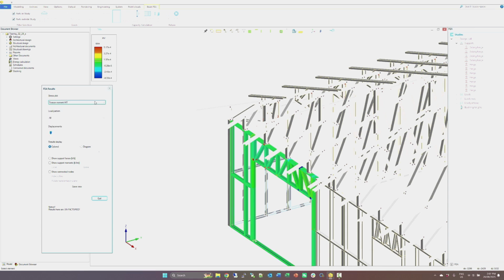We also have torsional moment, bending moment in the y plane, my. So the bending moment in the y-axis is the in-plane bending moment, and mz is out of plane. Shear force is out of plane shear force here in qy, and qz is in plane shear force.